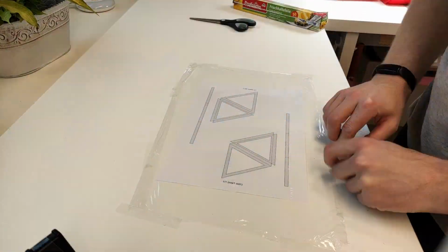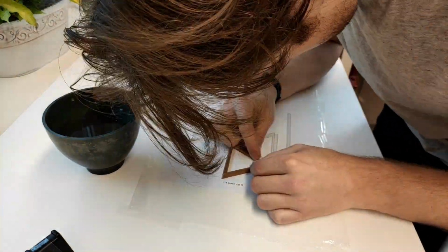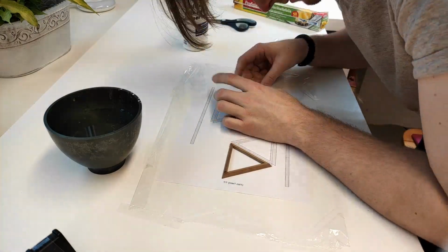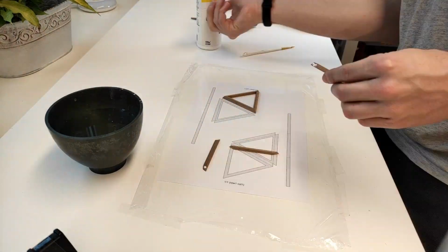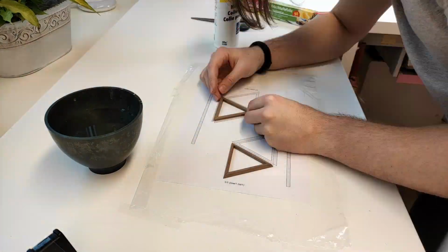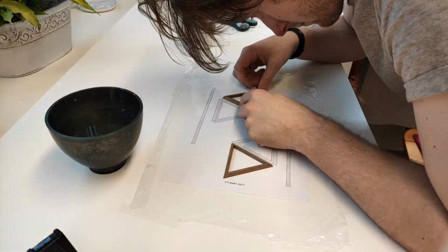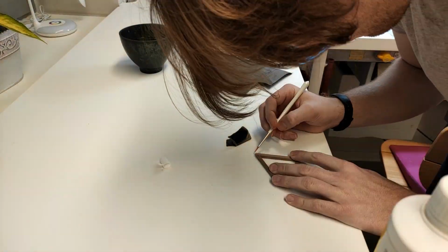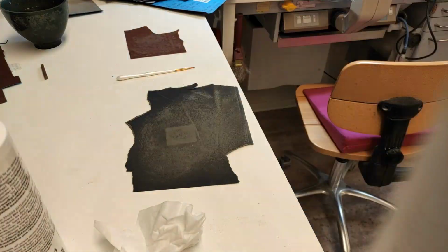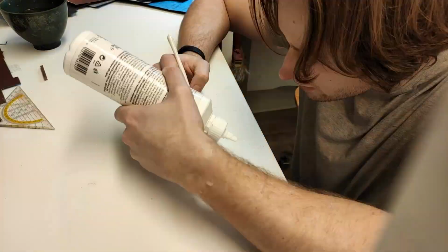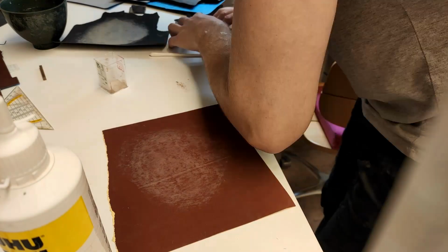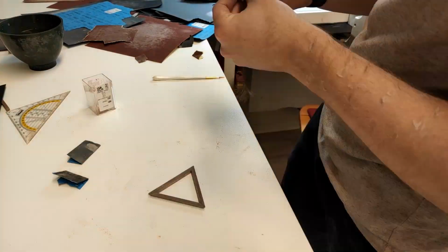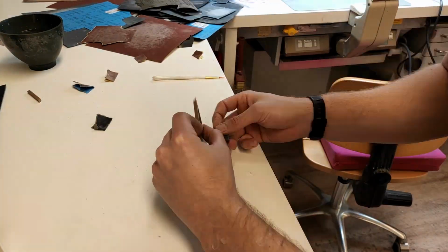Another thing I used Pepakura for was to print out the shape of the triangles for the icosahedron faces, so that I could glue the triangles on top of those templates together, so that I could be sure that all of the triangles had the exact same shape and size. After I glued the triangles together, I fixed some minor imperfections using just some wood glue and sawdust, and then sanded all of the wood down to 2000 grit. The sanding part for me is usually the most time consuming and boring part, but it really makes the model look more professional in the end.